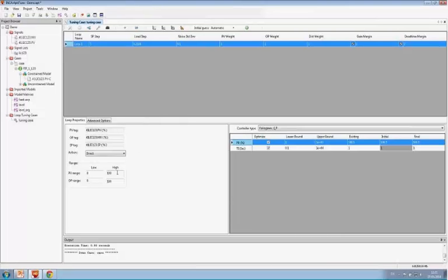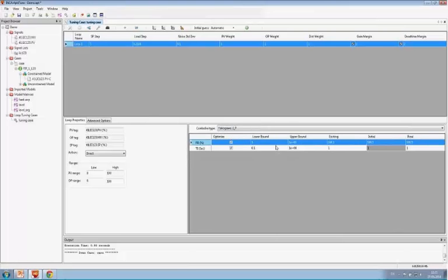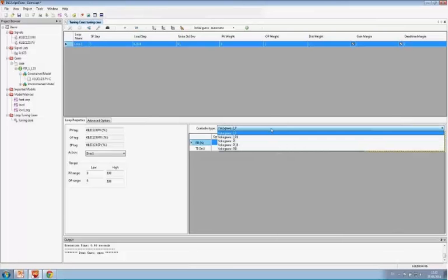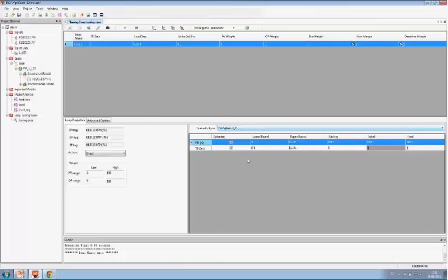Now in this case, the ranges are 0 to 100% because it's the level, and the operating range is a valve, so it's also 0 to 100%, but this could be different. And here on the side, we can choose which mode the PID block is in. And in this case, the mode was I on error and P on measurement. So I'll leave that.